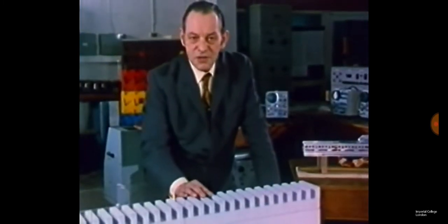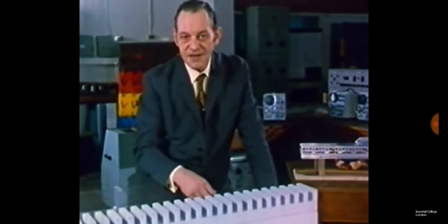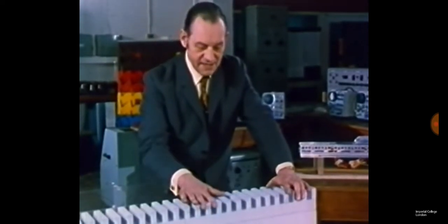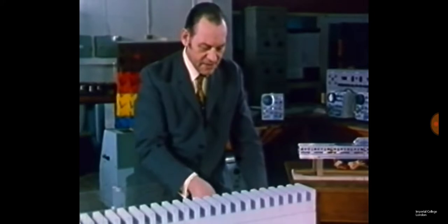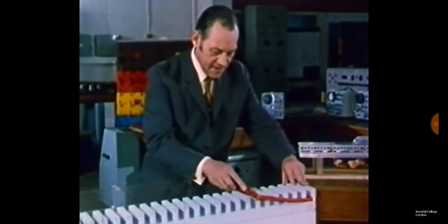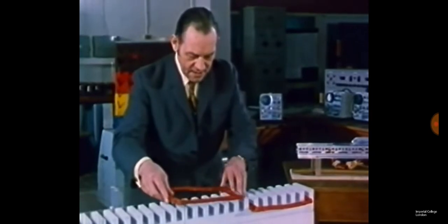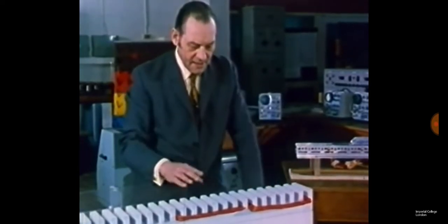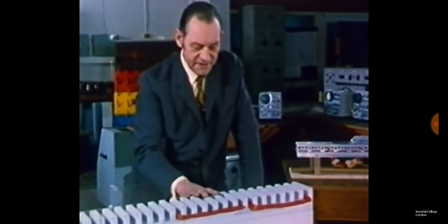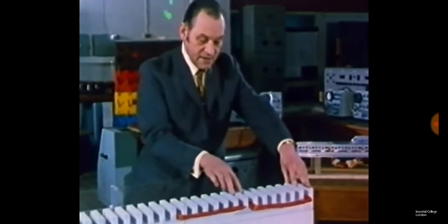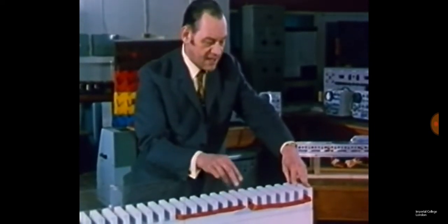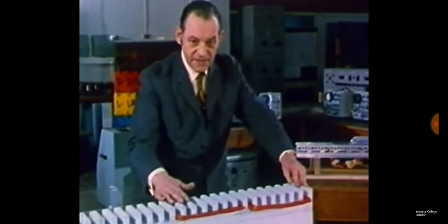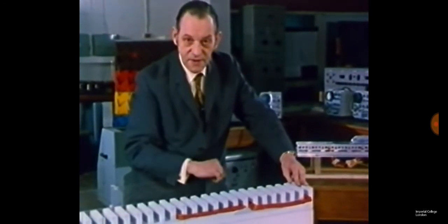I'm going to show you just one or two of the problems that are associated with trying to make a high-speed linear motor. This block represents the iron part of the motor, or its magnetic circuit. And it's into the slots of this that we're going to put the electric windings. We might decide to put one in there and one in there, so as to make this a north pole and this a south. The question is, what fixes the speed of travel of the field? Well, if you're feeding the coils from a 50 cycles per second supply, then the field will travel from there to there in a 50th of a second. And so you can work out the speed. And you see that the speed fixes the length of the coils.